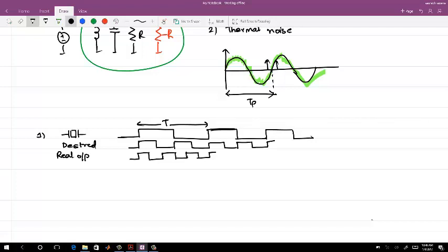In an ideal clock, every rising edge defines that you covered this much time in an absolute sense. What I desired was that the rising edge of the output clock should happen twice in every reference period. But what came out was actually 3 rising edges.